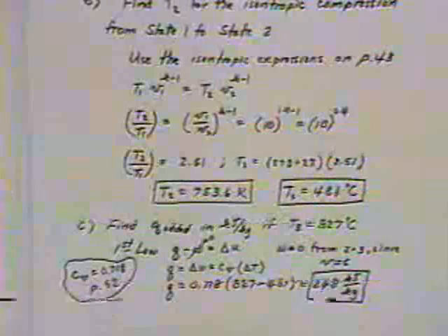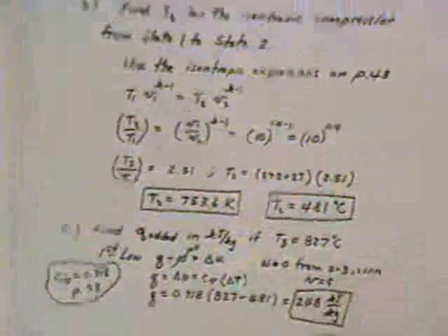the first law considerations. And so you go through and determine that W is equal to 0 since it's a constant volume process, therefore the first law reduces to Q is equal to delta U, and so that's equal to C sub V times T2 minus T1. So to avoid the problem of having to use an answer from a previous question in order to determine the answer to C, very likely both of those temperatures would be given. And so from there you would just go through and calculate the change in internal energy.